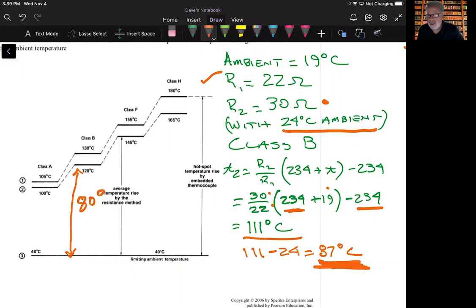And these would be the things carried out prior to production of a machine, when you're trying to make the determinations of class and so forth, and how the particular machine is sold. He says, the final word of caution, temperature rise standards depend not only on the class of insulation, but also the type of apparatus.